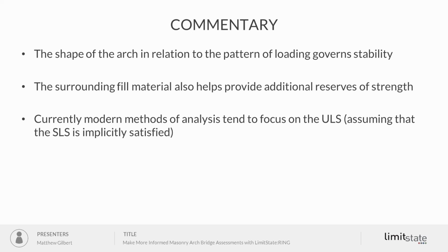The other thing to note at this point is the shape of the arch in relation to the pattern of loading that governs stability. So it's important when you're doing your assessment to carefully measure the shape of the arch profile, and also have a look at the pattern of loading that your traffic is applying.